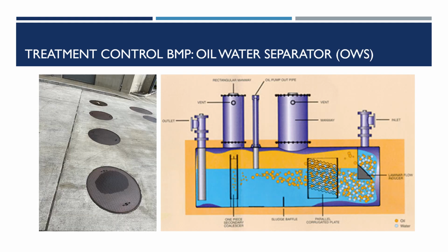An oil water separator, OWS, is primarily designed to remove oil, jet fuel, gasoline, diesel, other water-insoluble hydrocarbons, floatable debris, and settleable solids from stormwater runoff. The two commonly used OWSs are the conventional American Petroleum Institute, or API separator, also known as the baffle type, and the coalescing plate separator. Both use gravity to remove floating and dispersed oil.